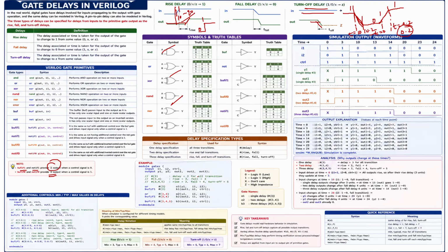And then gate delays, meaning we can represent delays. What is the delay we are representing? It is the hash delay. Hash 10 or hash 5, or hash 2. In this way the delay will be represented. In every transition you are representing delays, meaning 3 unit delays we are waiting, but sometimes we are representing maximum comma minimum delay.